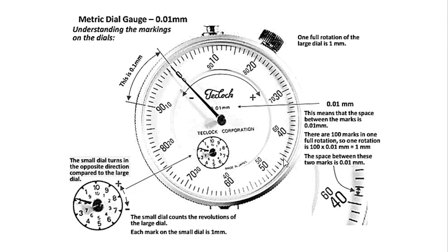Since the graduation from here to here, the discrimination, you can see the big one is halfway through from 40 to 50. So from here to here is going to give you 0.1 millimeter, because one step is 0.01, and 10 of them is going to give you 0.1. That tiny little step is 0.01.